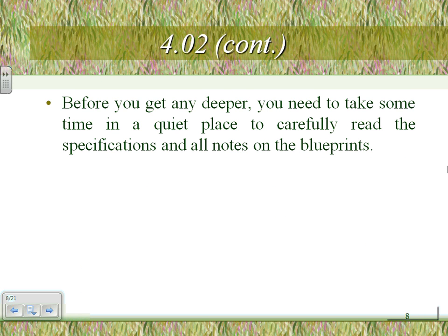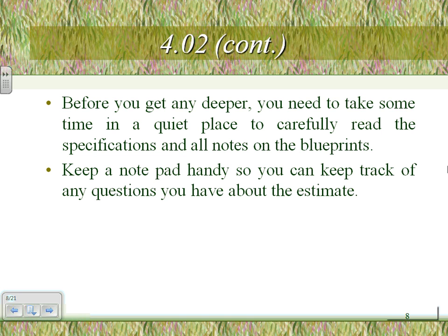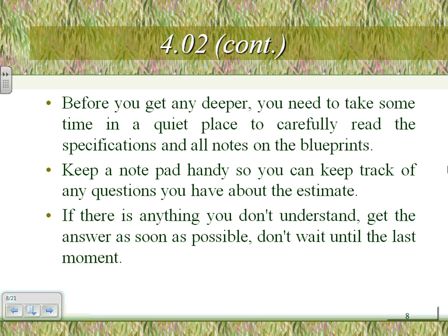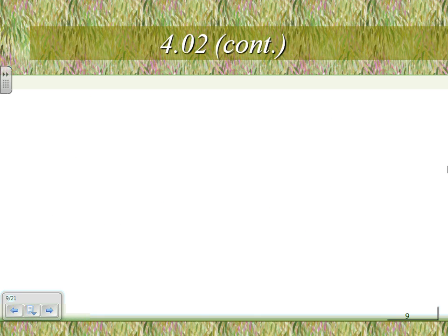Okay. Get to a quiet place and read the specification. Before you get into it, make sure you read the specification and the blueprints, will ya? Read in a quiet place where you can't be interrupted. Keep a notepad handy so you can keep track of the questions you have. Estimate bid. Any question that you have and anything you don't understand, get the answer as soon as you can.